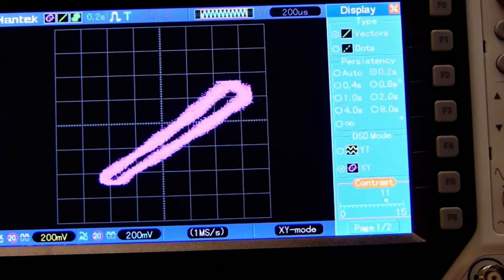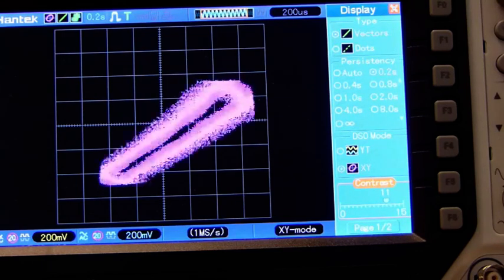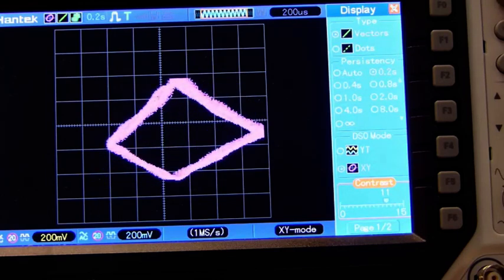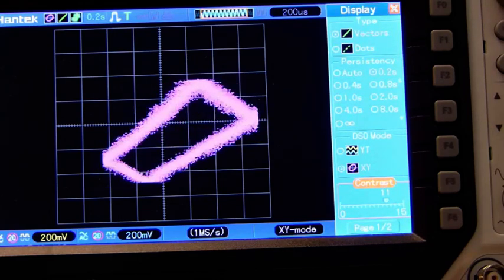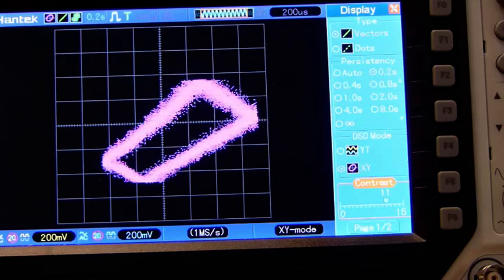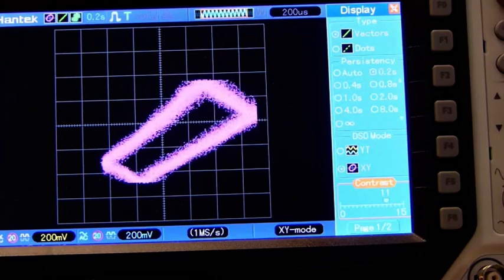And if we change the frequency of one of those VCOs a little bit more, then it goes out and in. So this is more or less what you maybe know from the Lissajous figures. This is also what you see when you use an oscilloscope in XY mode to check if two frequencies are more or less the same. Similar structures appear on the screen. But in this configuration you must consider that we have here two VCOs mutually influencing themselves in some kind of total chaos.